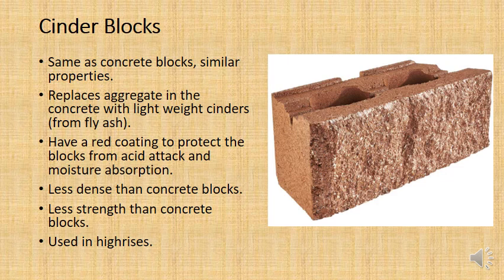And so the strength of the cinder determines the strength of the block. And so they're actually very weak compared to concrete blocks. A concrete block will maybe have a strength of 5 to 20 megapascals. A cinder block might be a maximum of 5 megapascals. So that's a big thing you need to remember.